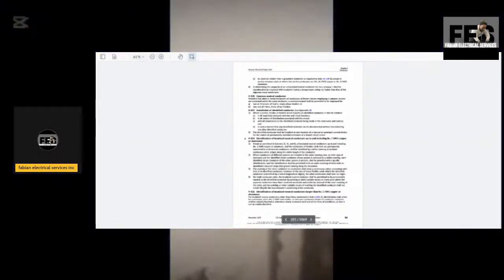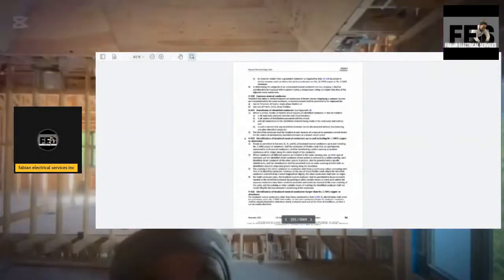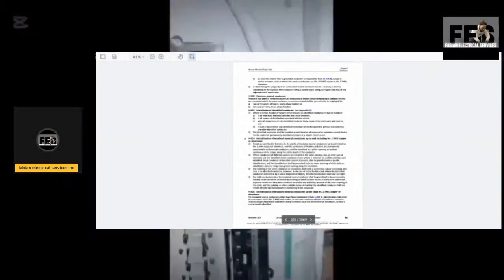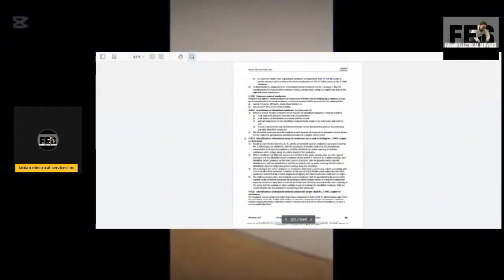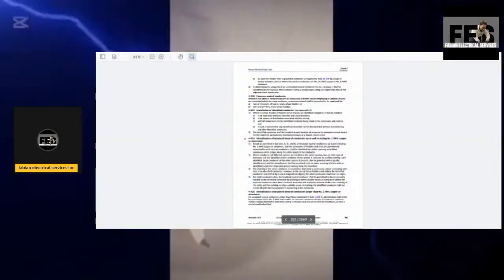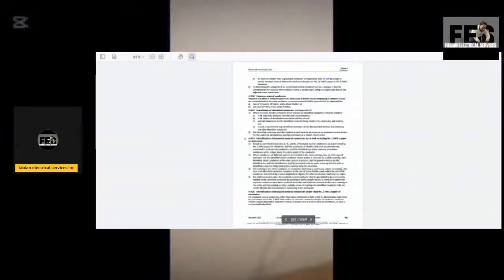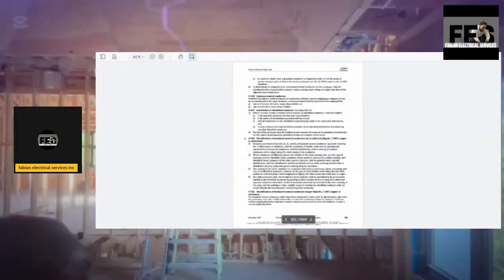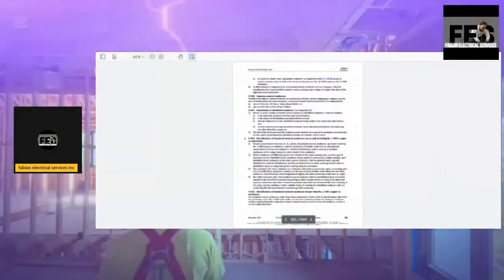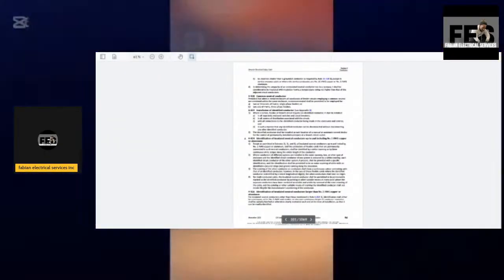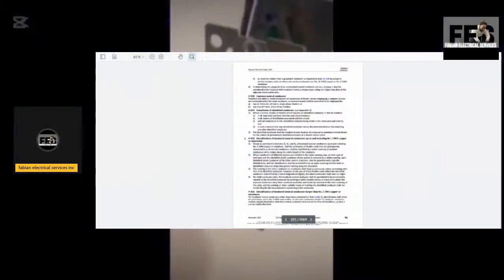Where conductors of different systems are installed in the same raceway, box, or other type of enclosure, and the identified circuit conductor of one system is colored by a white covering, each identified circuit conductor of the other system, if present, shall be provided with a specific identification, and the identification shall be permitted to be an outer covering of white with an identifiable color stripe, I guess not green, running along the insulation.